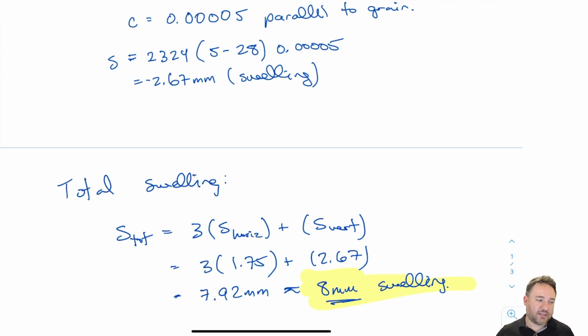In terms of shrinkage like this, probably 1 significant figure is enough, because remember, we have the difference between radial and tangential shrinkage, like we saw in the moisture content video, and we don't know which direction it is or what combination of directions. It depends on how the lumber was sawn from the log, like whether it is quarter sawn or whatever. In addition to that, the actual shrinkage coefficients are also very rough numbers.